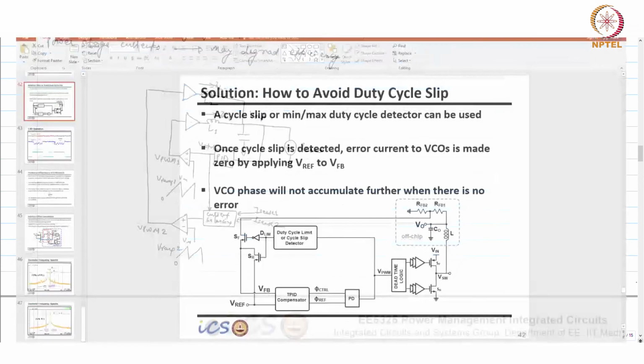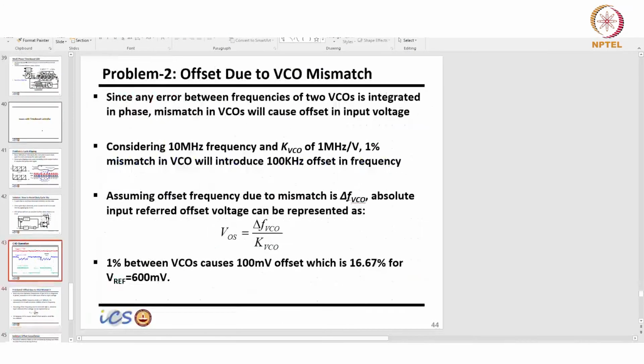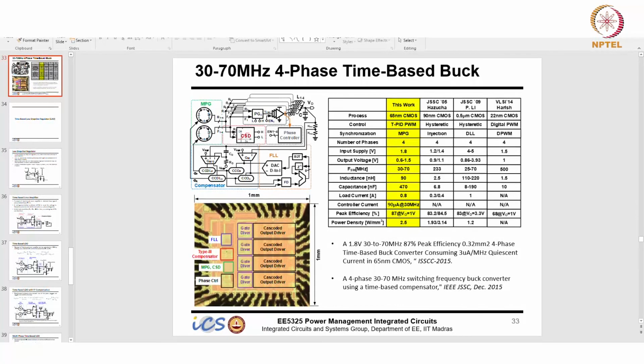And that's what we did here actually, if you see. Here it's 1 to 4 phase we are tapping, and this whole VCO is running at, if it's 70 megahertz and 4x, 280 megahertz actually. That's what this VCO is running at.